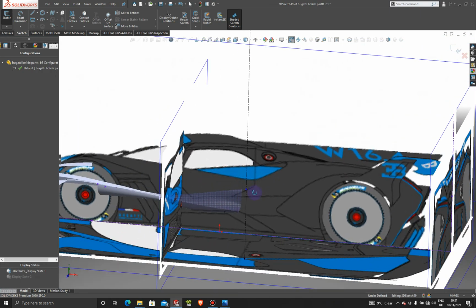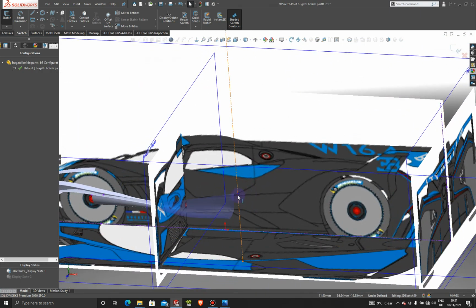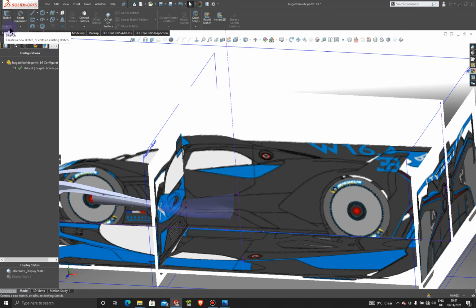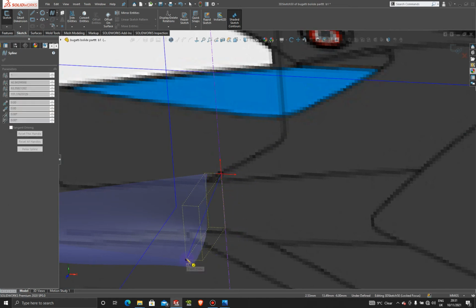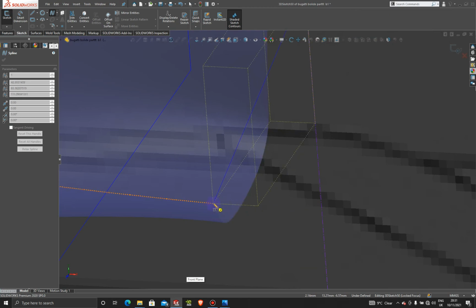Alright, so that's good. So now we determine that point, and we can come on to this section here, which will then be able to create that curvature. Okay, so let's exit from here and jump into our 3D sketch, 3D spline, and let's grab onto this point, and we're just gonna drop it on this edge here.